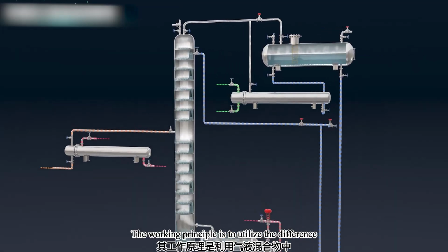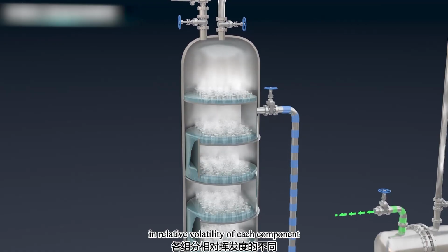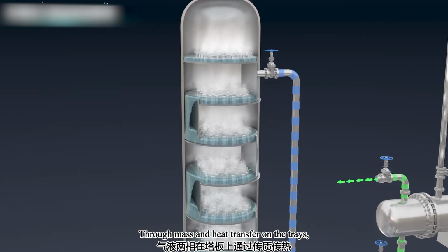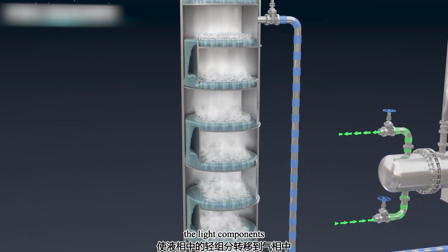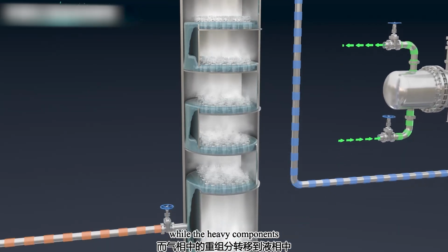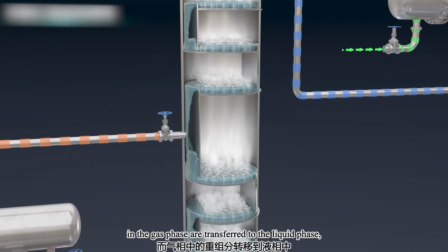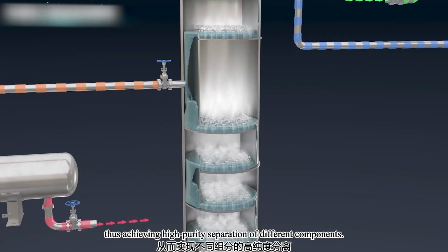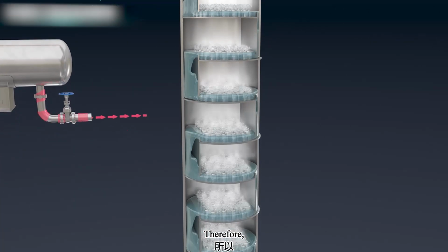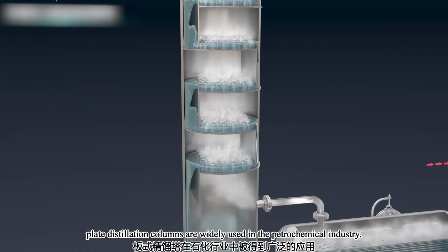The working principle is to utilize the difference in relative volatility of each component in the gas-liquid mixture through mass and heat transfer on the trays. The light components in the liquid phase are transferred to the gas phase, while the heavy components in the gas phase are transferred to the liquid phase, thus achieving high purity separation of different components. Therefore, plate distillation columns are widely used in the petrochemical industry.